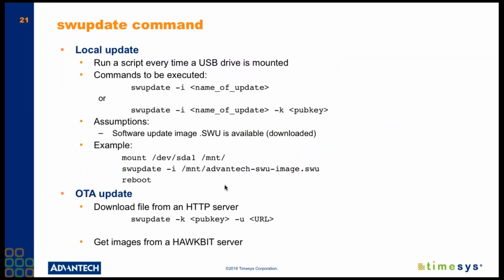SWUpdate is a command, so here are different incarnations of how I would use SWUpdate to perform a local update, as well as to access a remote HTTP server from the target device, from the Advantech IMX6 device, to pull down the SWU update for that device. Okay.